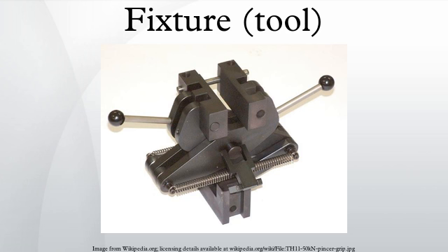Drilling fixtures: drilling fixtures cover a wider range of different designs and procedures than milling fixtures. Though work holding for drills is more often provided by jigs, fixtures are also used for drilling operations. Two common elements of drilling fixtures are the hole and bushing. Holes are often designed into drilling fixtures, to allow space for the drill bit itself to continue through the workpiece without damaging the fixture or drill, or to guide the drill bit to the appropriate points on the workpiece. Bushings are simple bearing sleeves inserted into these holes to protect them and guide the drill bit.